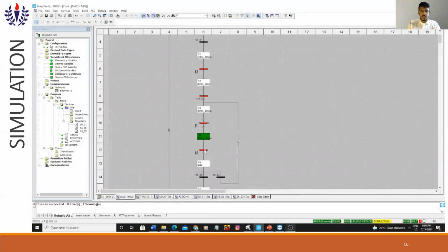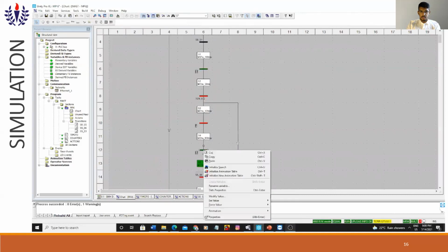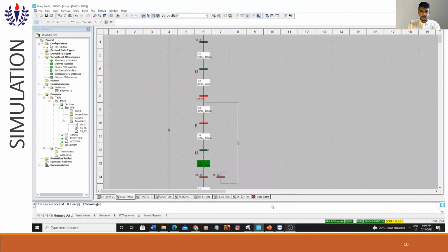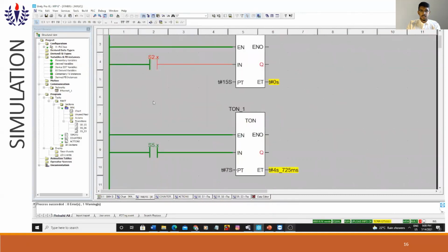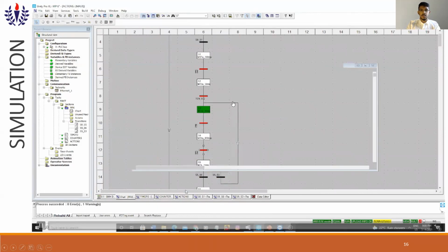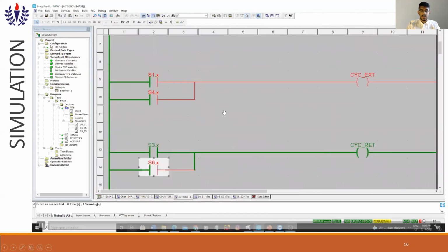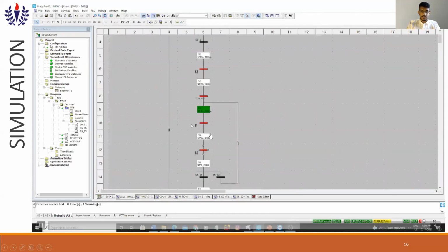We'll see here that once the low position is met, the timer starts for 7 seconds. As you see, the loop is completed here. And after 7 seconds, the process repeats. As we had mentioned, now the cycle count is going to be 2. In the previous step, it was cycle number 1. Now cycle number 2, so it's going to go back and repeat to S3, where the drilling is going to be on and the cycle is retracting.